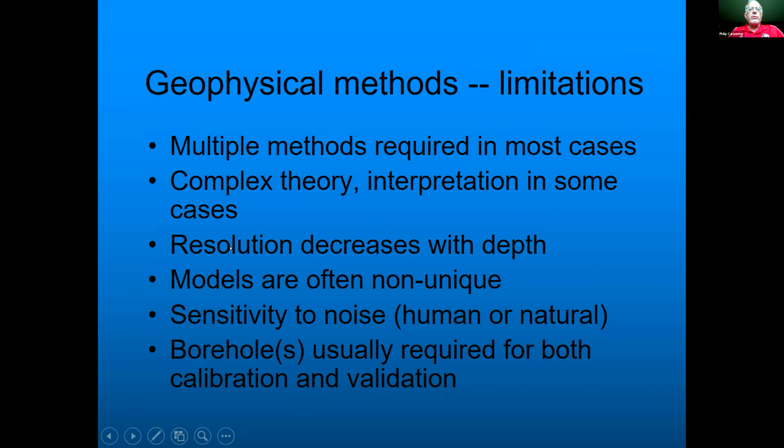A basic rule is resolution decreases with depth. So the deeper you go, the less detail you can see. Models are often non-unique. We'll see some examples of that in these cases I'm going to show you. Sensitivity to noise is a biggie, especially in landfill situations, where you've got trucks moving around and sometimes electrical noise.